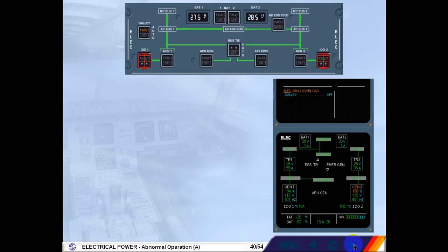On the engine warning display, read the title of the failure. Observe the generator and load indications in amber on the ECAM electrical page, indicating that the load is abnormal.